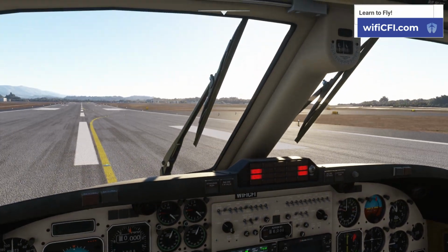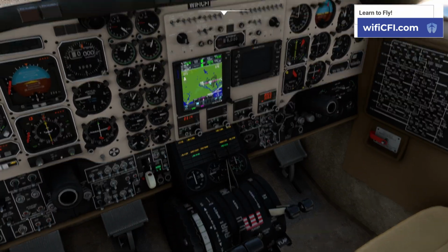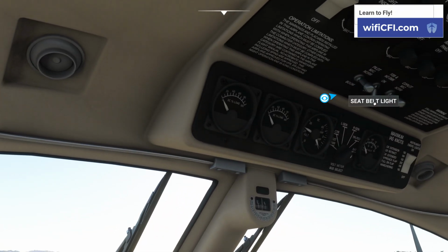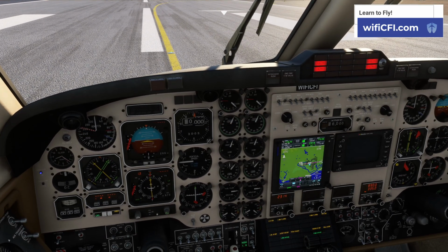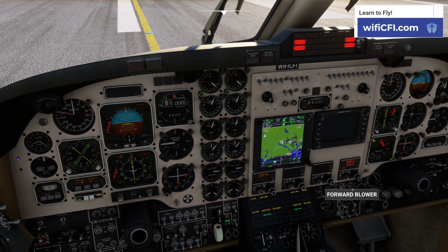Cabin sign is usually over here in the 200, but up here, 350, we can put that to fasten your seatbelt, no smoking. We can get that on. Vent blower is auto. We've already got it down over here to auto. Cabin temp mode is off right there. Aft blower is off. Radiant heat I don't think is even in this airplane, so yeah, aft blower is off. Good.